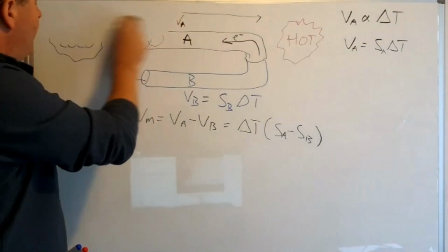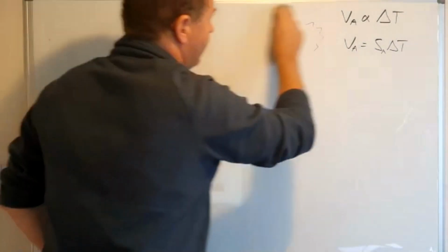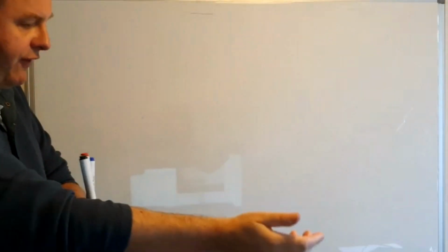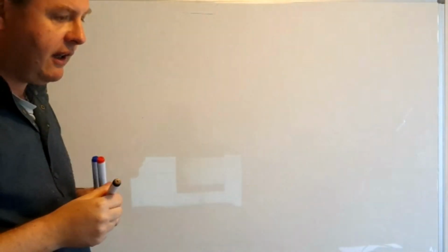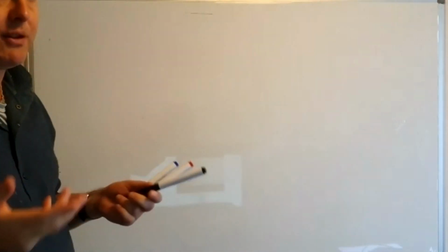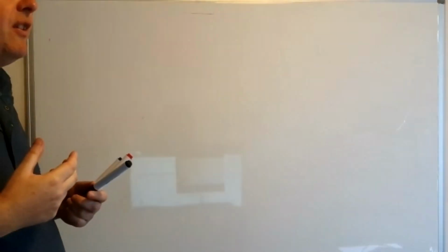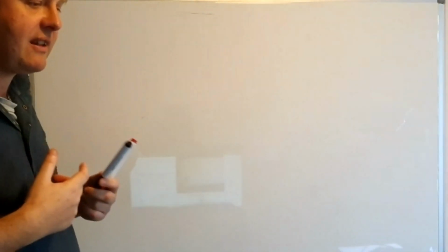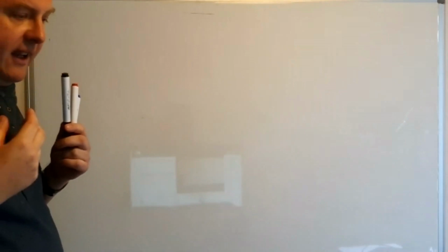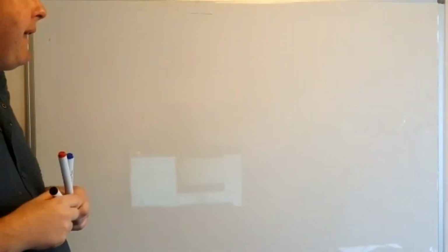So just as a final example, we can talk about different resistor type sensors. You might remember that in your first year tutorial, where you were talking about a type of sensor being used to measure device temperatures. This was a type of sensor that had a resistance that went up exponentially with temperature. This is a classic example of a sensor which involves charge carriers conducting through the system but undergoing a series of energy barriers.